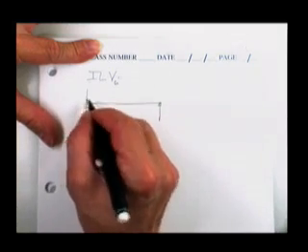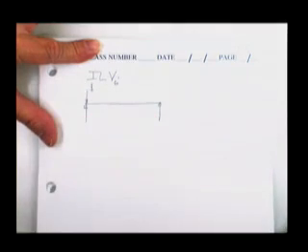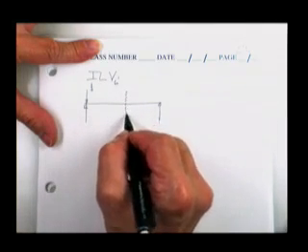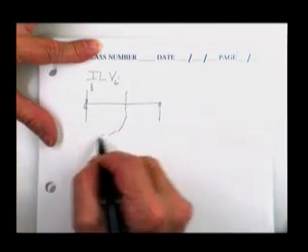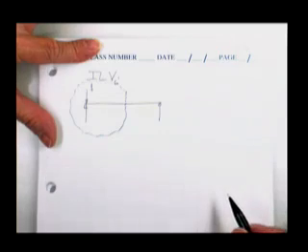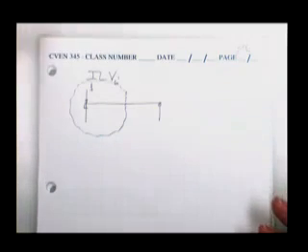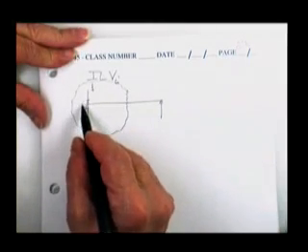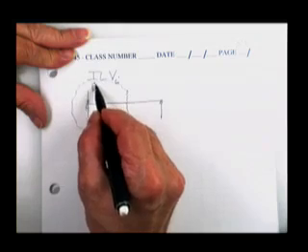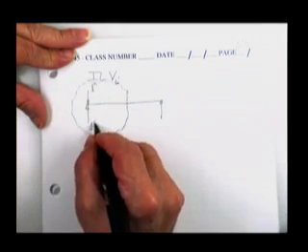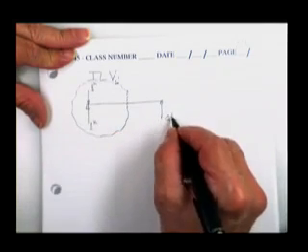First off, we put the unit load just barely on the span, and we cut the beam at the 6-foot mark, and you take either side you want for a free body. It's your choice. Incidentally, I now know these reactions. I'm just going to go pull them off a previous page. When you put a 1 kip load just barely on the beam, it causes a 1 kip reaction and a 0 kip reaction.